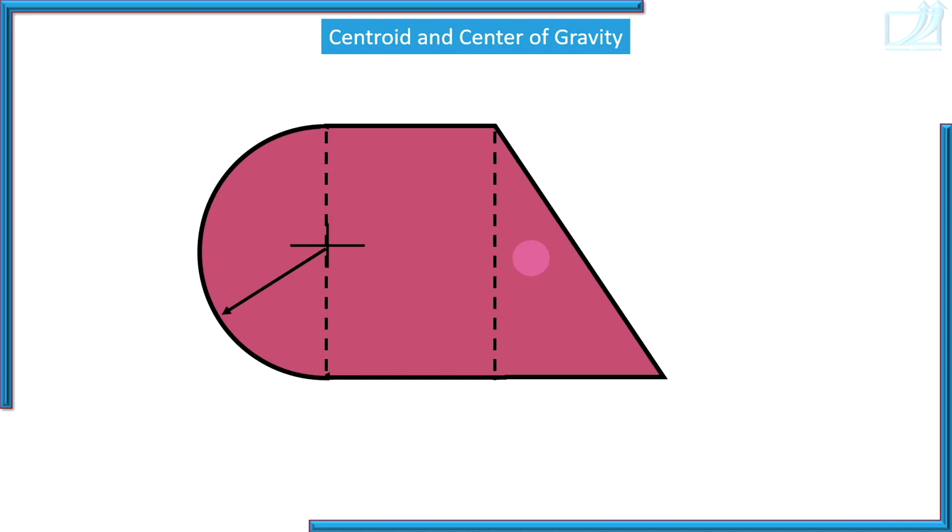Similarly, now in this video, if the given shape is combination of standard shapes, then how to find centroid we are going to study. And to find a centroid of such a composite shape, you must know location of centroid of standard shapes. That is location of centroid of semicircle, location of centroid of rectangle and location of centroid of triangle. If you know positions of centers of these three shapes, you will be able to find a centroid of this entire shape. So let's have that information.